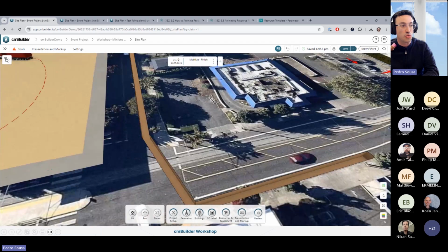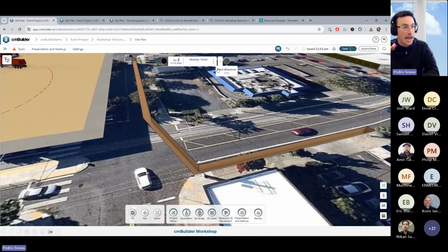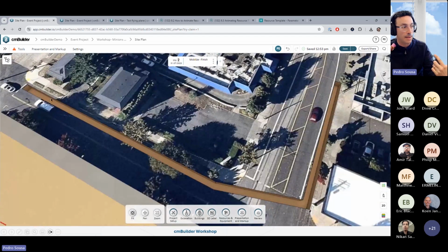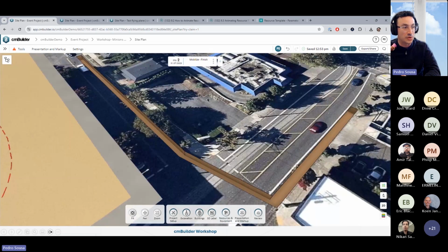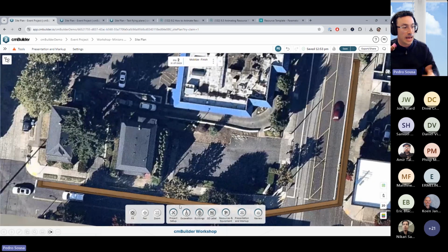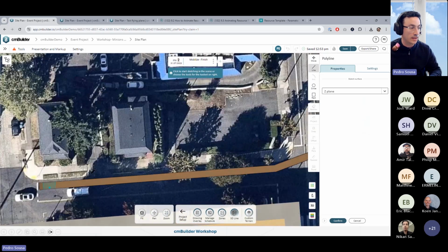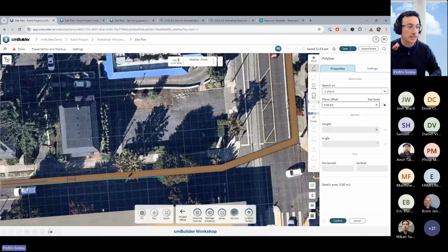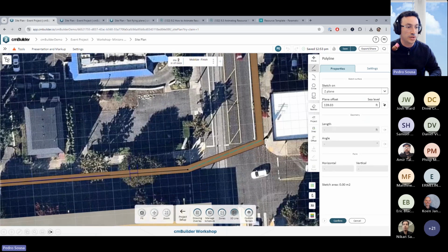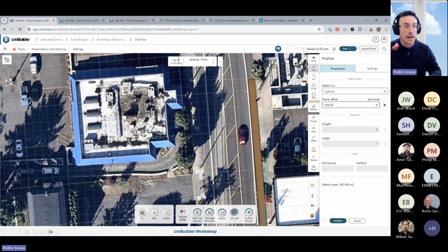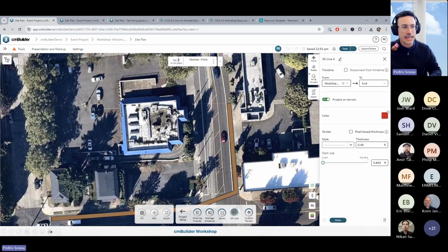a trench over here, an excavation for a trench. I want to show a pipe going in through this trench, right? So what I will create now is a 3D line where I can look from above, and I will create this line to follow this trench, and this line is going to represent my pipe. So when I hit confirm, I can't see the line.